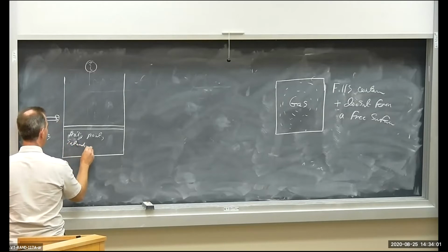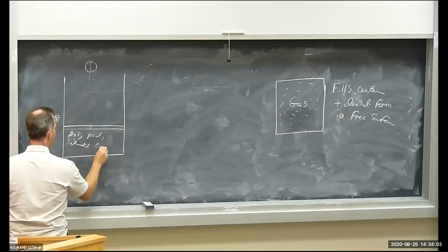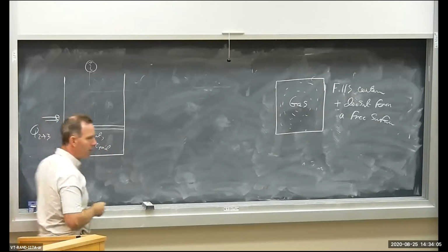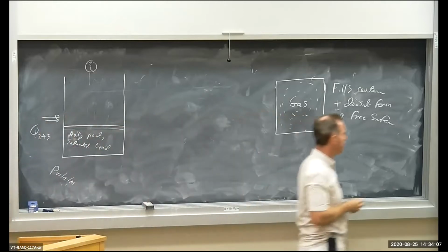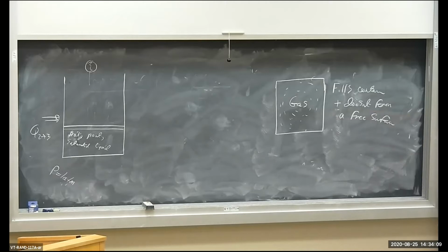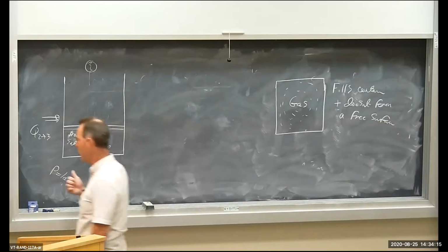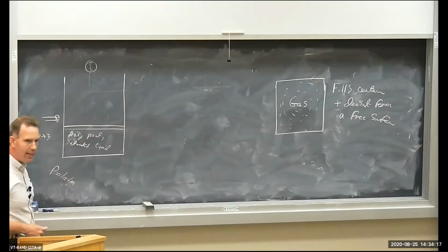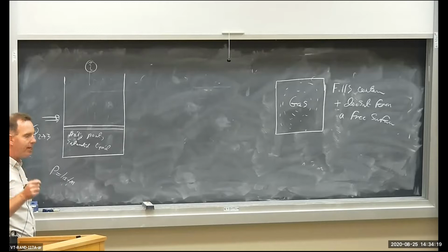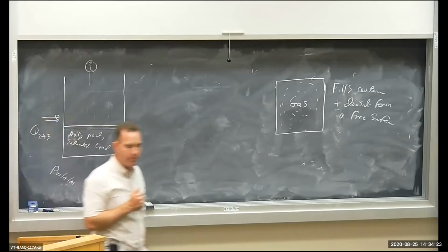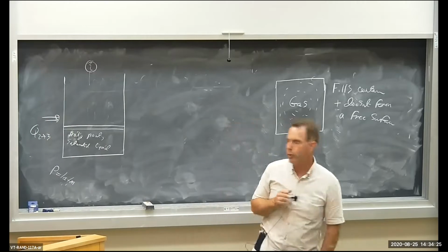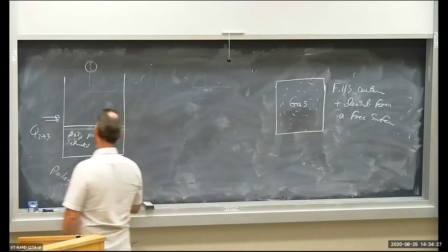Saturated liquid. That means liquid just ready to boil. We started off with liquid water at 25 degrees C. We heated it up to 90. It's still liquid. And then we're going to heat it up until it's just ready to start boiling. What temperature does water boil at 1 atmosphere? In metric, it's 100 degrees C. So T3,